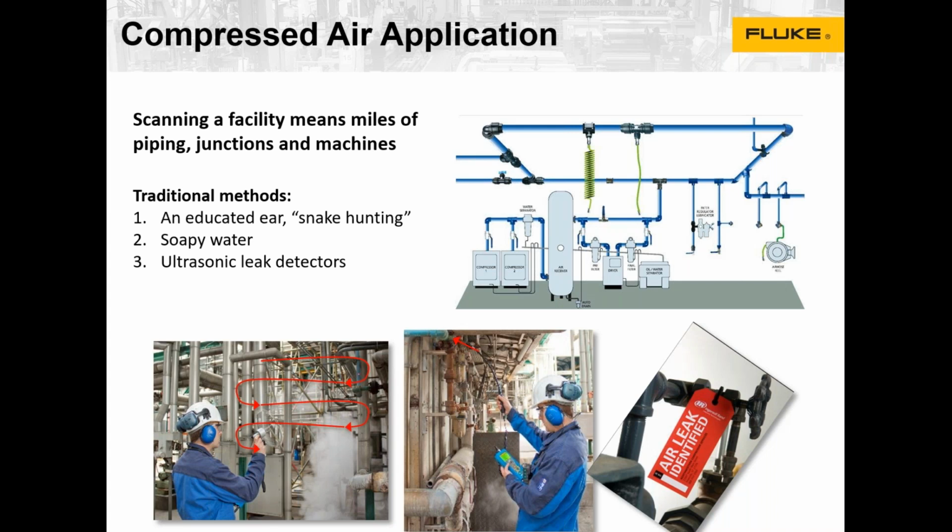They also told us that some of the methodologies or technologies that were out there for finding leaks were just really time consuming or difficult. So customers were actually using soapy water. I know I've done this to find leaks in the past, and maybe you've done that too, where you fill a spray bottle up with soap and water, and then you can go around anywhere that you would anticipate a potential leak to be, and you can spray that area, that fitting or that connection or whatever the case may be. And where there's a leak, you've got pressure coming out, and so it causes the soapy water to bubble. And so where you see bubbles, you've got a leak, but it's really time consuming and difficult to do in places that are hard to reach or hard to access.